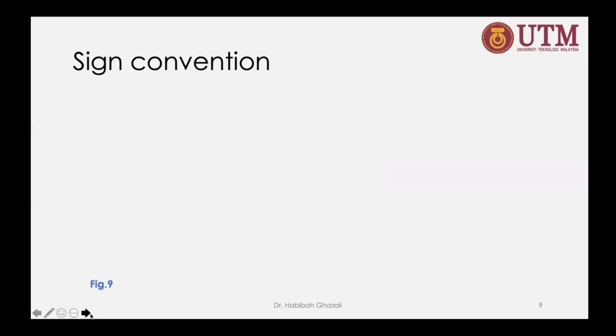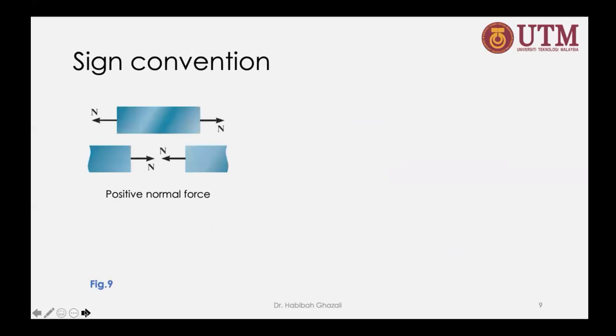Everyone can do this? Now the sign convention. If the material is going through external forces that are going to elongate it, for example if you try to elongate this rubber band, which is a good example, the internal forces are going to try to resist that elongation. So the resisting force, we put in the sign convention as positive.